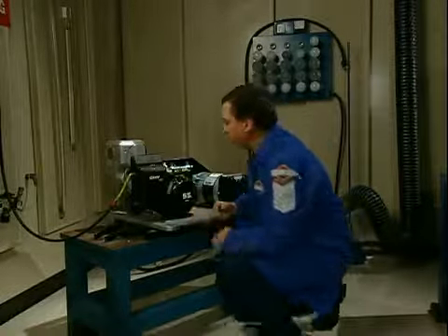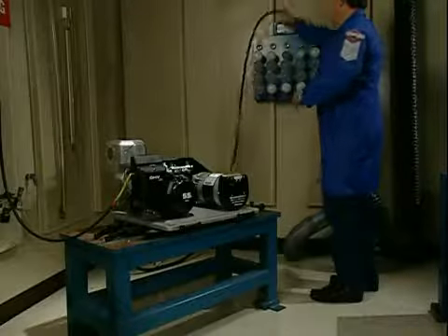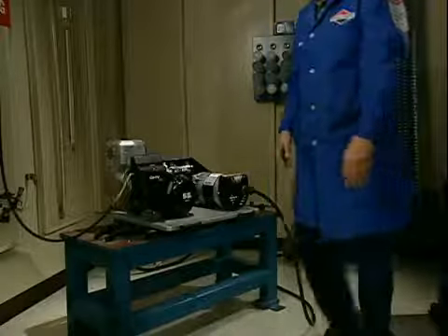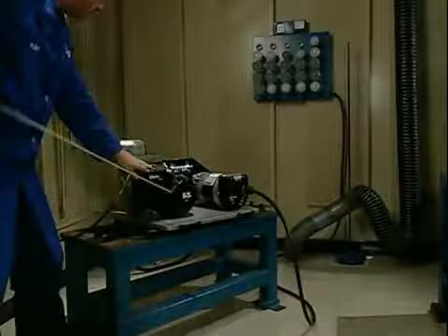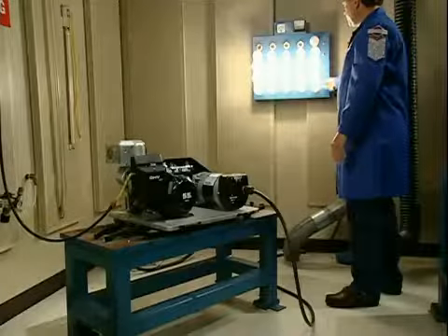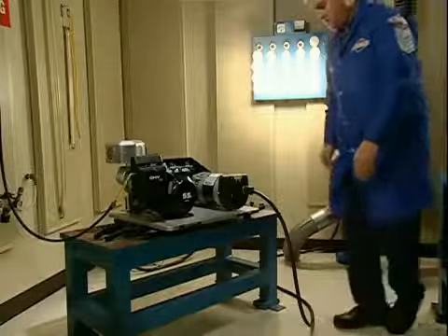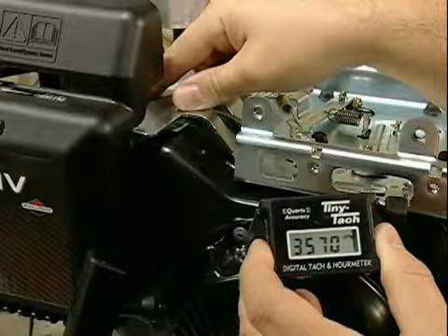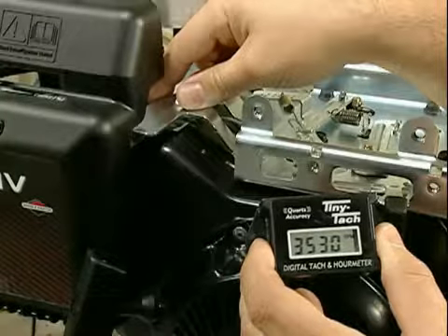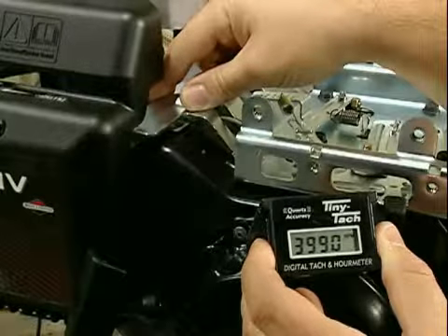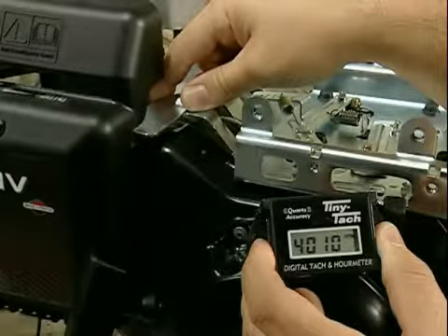For the purpose of this discussion, we will assume that the engine and equipment are properly matched. However, application engineers use the following approach as a rule of thumb to help establish a good marriage between engine and equipment. Make sure the engine is broken in at operating temperature and properly adjusted. Apply the maximum load that the equipment is designed to handle. Take an RPM reading with an accurate tachometer. Manually force the throttle shaft to wide open throttle. Take an RPM reading.